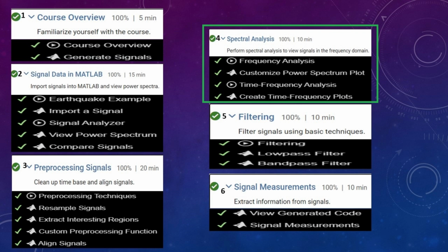D. Create time frequency plots. Tasks: create a spectrogram of the Wrangell signal. Set the frequency range from 2 Hz to 10 Hz and the power limits. Create a scaleogram and compare both visualizations. Determine which method better identifies local earthquakes.